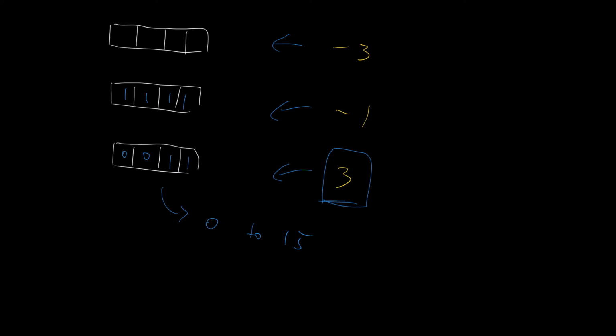So in fact, in 2's complement notation, in this particular case with 4 bits, the largest positive number we can write down is going to be 0111, which corresponds to the number 7. The number -3 is going to be 1101, and we'll explain why presently. Right now, the key point is, on the left, we have the representation used in a digital system, what is physically carried by the wires, and on the right is how we humans interpret what is being stored.